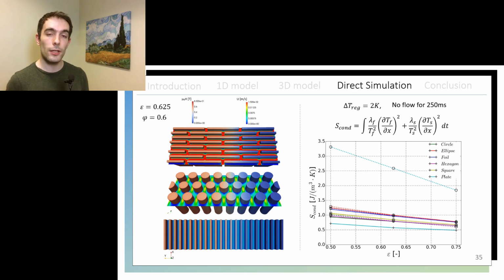Since we're keeping the mass flow of those surges constant and the tortuosity is higher, so the distance that the fluid has to travel is larger, the local velocity has to increase. This is exemplified on the left side of the slide.